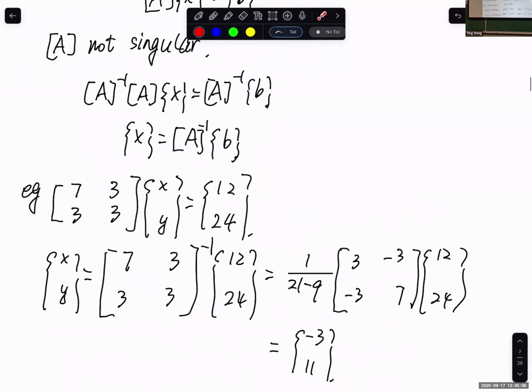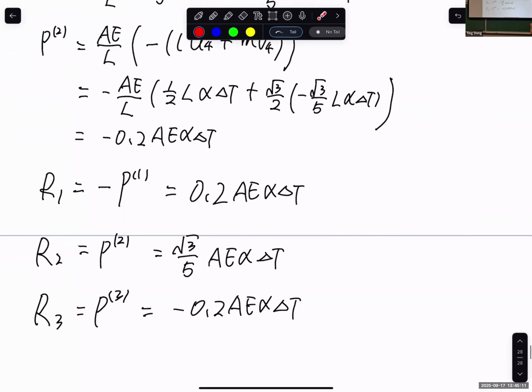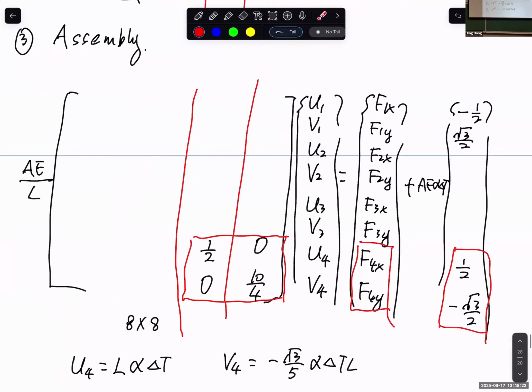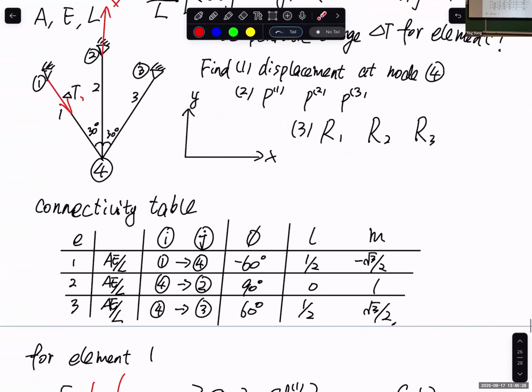Could we look at the bottom of the note? How does the intuition work for knowing if the internal force is positive or negative? Since this is the first node of an element, you add a negative sign. If it's the second node, it's positive. It has to do with how we define the convention. In my definition, this is the first node, so I add a negative sign, but for the second and third elements, these are second nodes, so it's the positive minus the first.